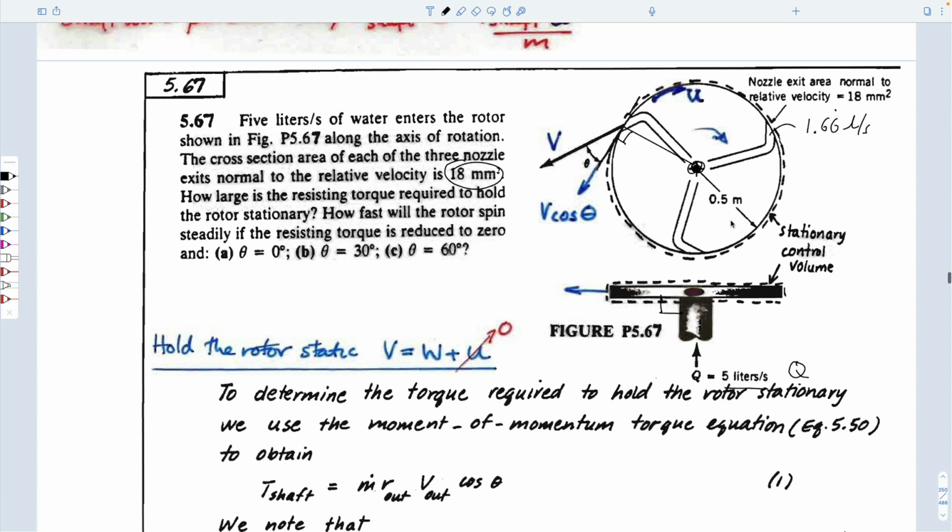And so the idea is, again, we have water coming up through the bottom here. It turns a right angle, and when it turns a right angle, we don't care about this portion here. We only care about the flow rate magically emanating at a flow rate here and coming out here. And so we only have this one to take care of. We've done the calculation with W coming out here. It could come out at an angle, and we could accommodate that.